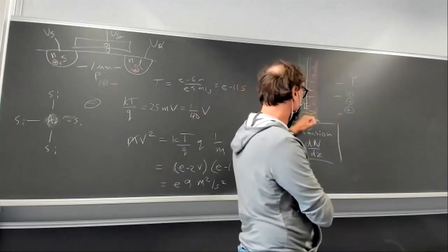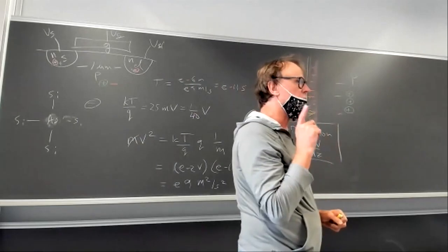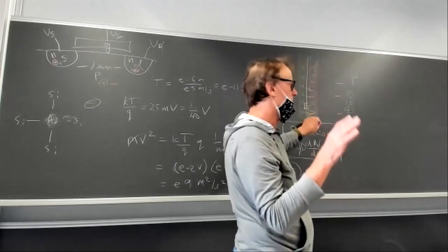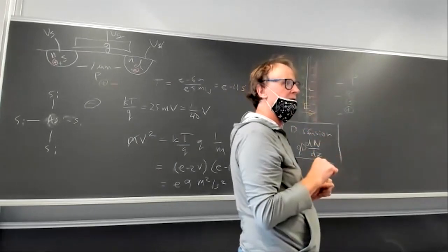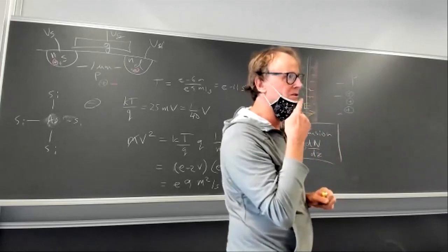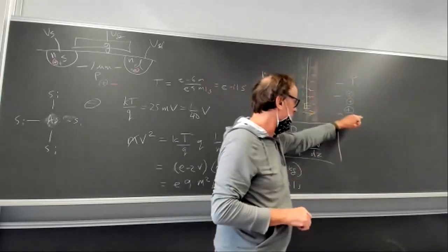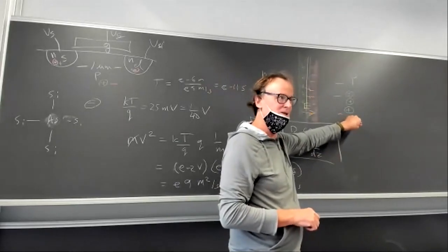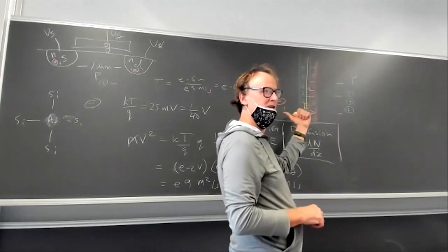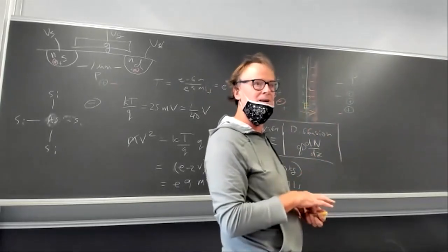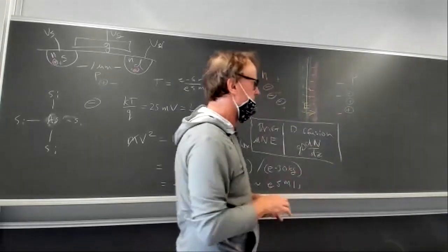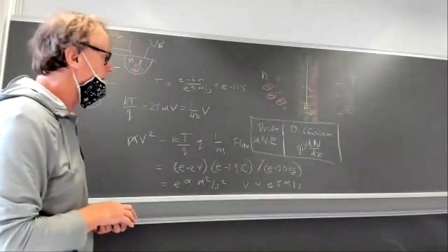And we know the electric field always pulls carriers home. The built-in electric field that builds up between oppositely doped regions makes carriers go home. You remember that if you're ever confused about it. It pulls the holes back home to the original p-type region, and it pulls the electrons home to the n-type region. It opposes the diffusion current. Is it clear? It must, because there can be no net current in the equilibrium.